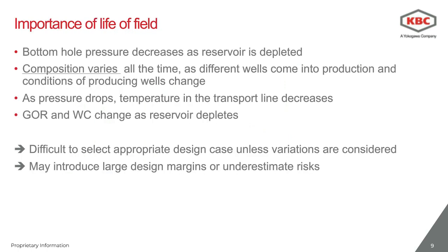Because this is an evolving field, one would expect things to change during the life of the asset. In particular, we know that the bottom hole pressure is going to decrease as the reservoir depletes. And we expect the composition of the produced fluid to vary for various reasons, one being the depletion of the reservoir, but also because different wells are going to be brought into production at different stages.